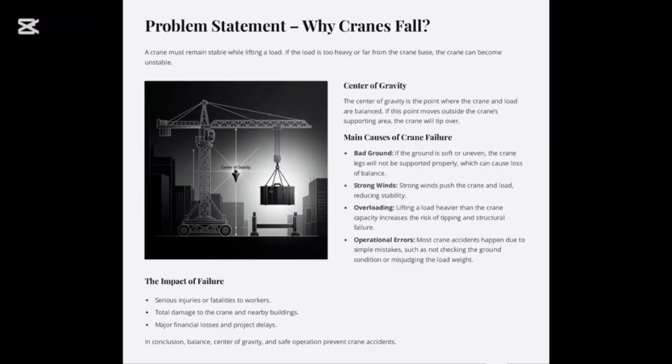Main causes of crane failure. Bad ground: if the ground is soft or uneven, the crane legs will not be supported properly, which can cause loss of balance. Strong wind: strong wind pushes the crane and load, reducing stability. Overloading: lifting a load heavier than the crane's stability limit increases the risk of tipping and structure failure.